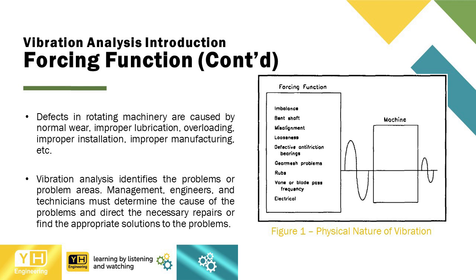Defects in rotating machinery are caused by normal wear, improper lubrication, overloading, improper installation, improper manufacturing, etc. Vibration analysis identifies the problems or problem areas. Management, engineers, and technicians must determine the cause of the problems and direct the necessary repairs or find the appropriate solutions to the problems.